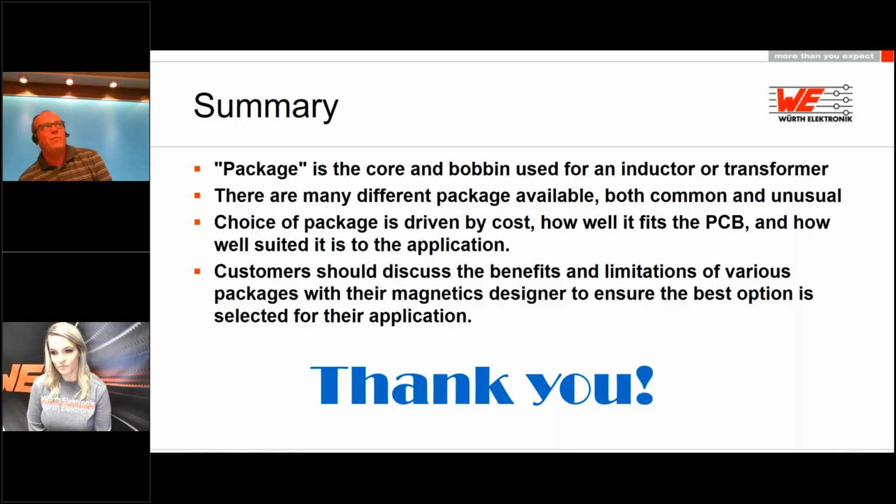And that's really one of the most unusual things about LLC as compared to all the other topologies. With flyback and everything else, forward designs, leakage inductance is a parasitic. It causes losses. Transformer designers try to minimize the leakage inductance as much as possible. Customers then ask the transformer designers to minimize it further.